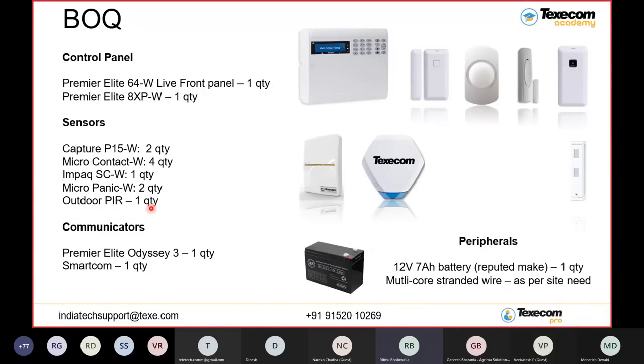And please remember one thing, Texecom sensors are used for indoor areas only. Whether it's a PIR motion sensor, magnetic contacts, vibration sensor, dual sensors, any type of sensors, the Texecom sensors are used for indoor areas. For outdoor PIR motions or outdoor sensors, there are multiple brands available in the market. You can use either one and connect it on our control panel.